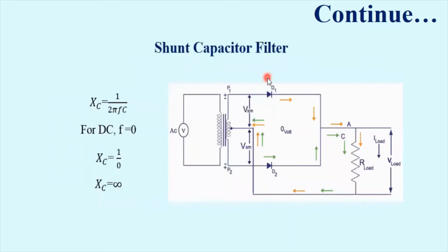So the DC voltage we will receive after rectification has some ripples and AC signal. For that we will need filter circuit. Here we will use capacitor filter for the process of filtration. This filter is the cheapest and the simplest filter. In this, we will choose a large value capacitor. So here I have the center tap full-wave rectifier circuit. In this circuit, I will connect the capacitor filter and check the response of the circuit.